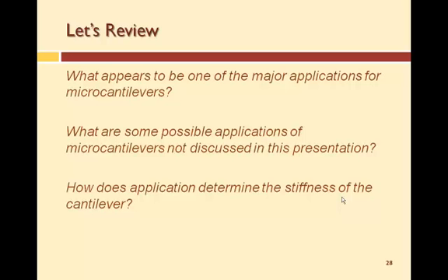One thing I read about along the lines of the energy harvesting thing is if you have a radioactive source, right, and you have high energy particles come off of it, you can create a charge difference. So you can create charges in a system. So now you're charging your cantilever, it'll get attracted to another oppositely charged or grounded pad, and you can get it to move, and then once it touches, it shorts out, right? Discharges, and the cantilever moves back to its original position, and the radioactive source starts to charge it up again.